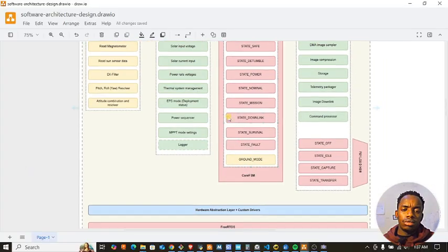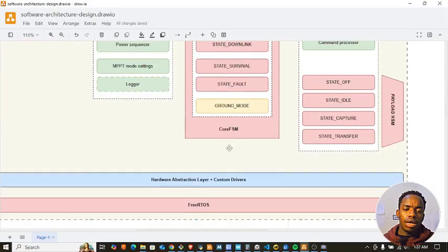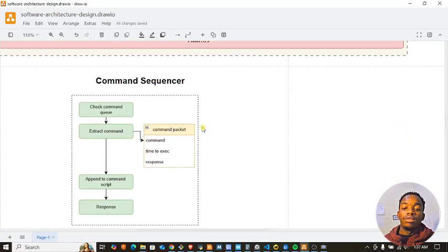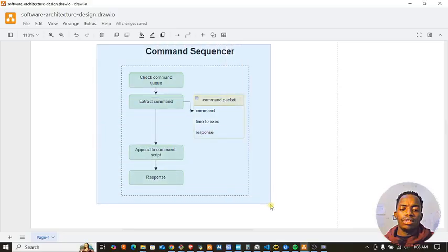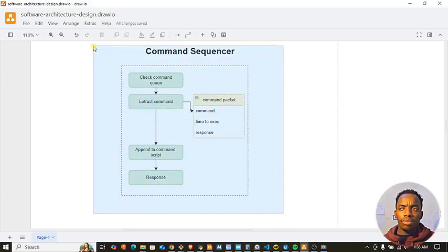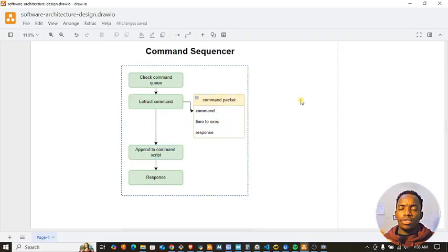So at some point, this OBC, or decision engine, will have to run. I think I should add some things here. It will run the mission, or we run the commands that have been stored, right? This is very, very critical when you want to make the CubeSat autonomous. Mostly it will come in handy when you want to do subsystems checks at regular intervals. So you can be checking the systems and storing the responses, and then we dump them when we are over a pass. Yep.